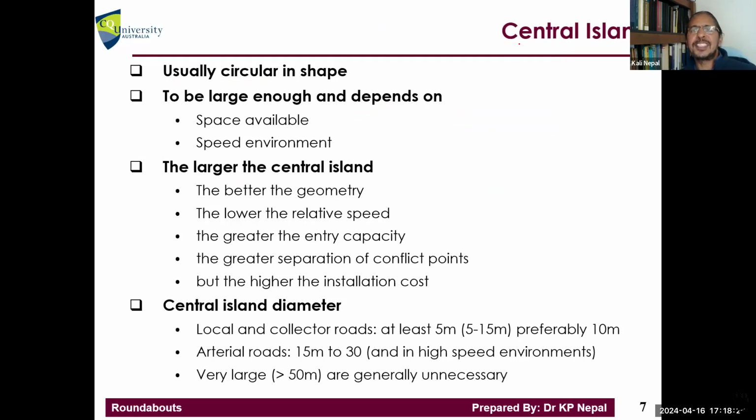Another terminology is the central island. You see the island in the center. Please don't plant very big trees in the center to obstruct the visibility. Some environmental people may want to plant trees and things in the center, since there's an empty space, but that is not the case, because we need to see clearly who is coming, whom we need to give way to. That's good. How big the roundabout is depends on the space and the speed.